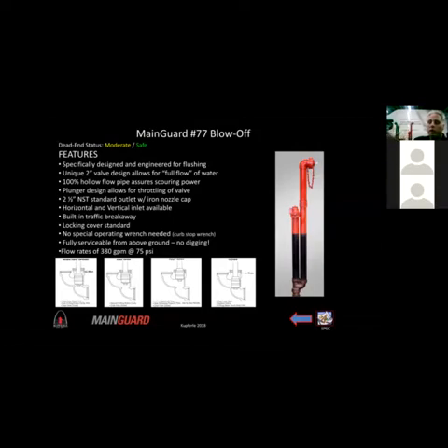All these hydrants weep to ground just like a fire hydrant. So they're freezeless hydrants that you can use year round in whatever area that you're in. We do deep buries of these, especially up in Calgary, Alberta, and that area up in the Alberta province. We do 10-foot buries in some places up there. So a lot of these we can do, but the plunger comes up out of the way and you see the water bypasses the plunger. So the plunger comes out of the way and the water goes past it into the second pipe.